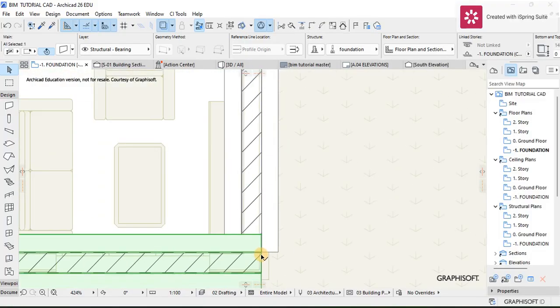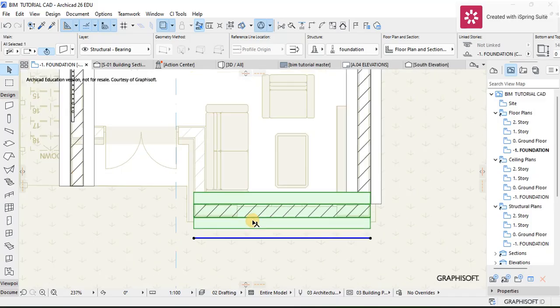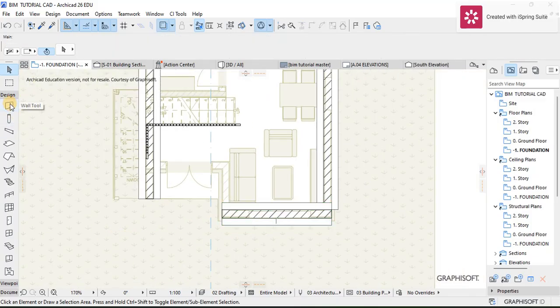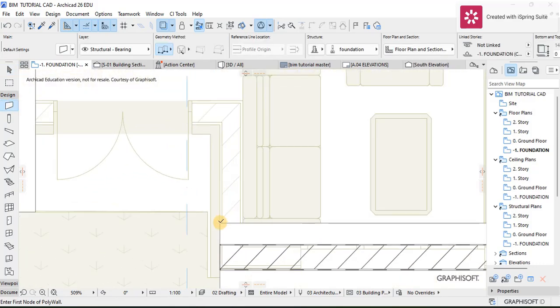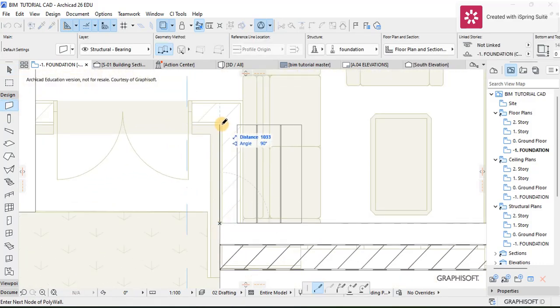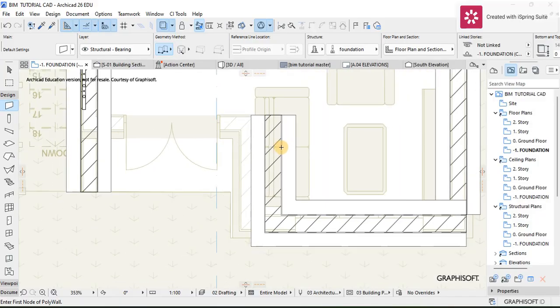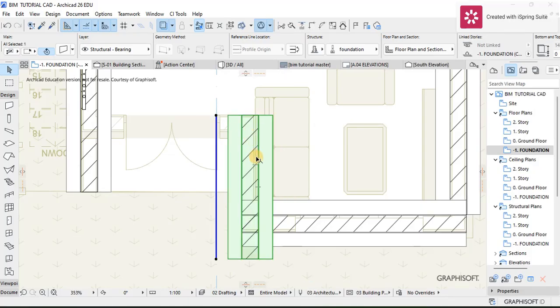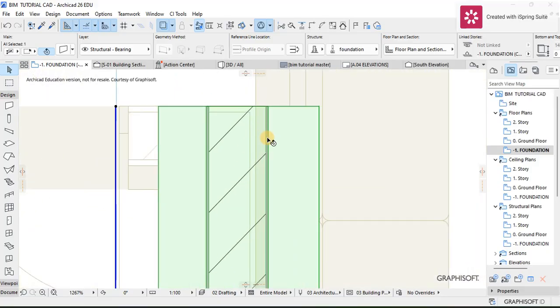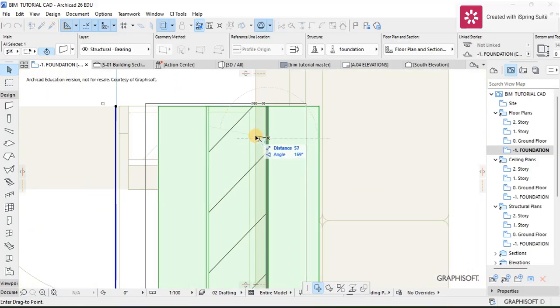Yeah, so here it is. Then we're going to drag the next one too. Don't worry about how they're joining. I'm just going to use the joining tool for the wall. So I'm going to drag another one here. I'm going to have to select this one and drag it again to be just below the masonry block on top of it. So make sure it's on top.